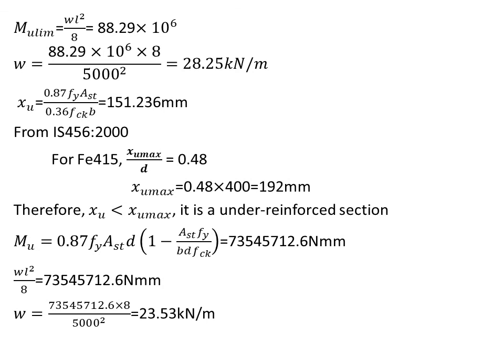And I know there's a confusion for the last question, but this is how we calculate it. This subject is basically all about assumptions, and when we check the type of section, we have to check both conditions. Even if we found out in the question what the question asked for, we have to check whether our assumption is correct, in what section it is. In this question, we assumed it to be a balanced section, but it turned out to be under reinforced, and hence Mu limit had to be calculated again, since it was only mentioning ultimate UDL. It's how the procedure follows for each question.